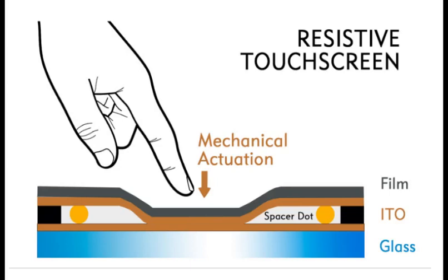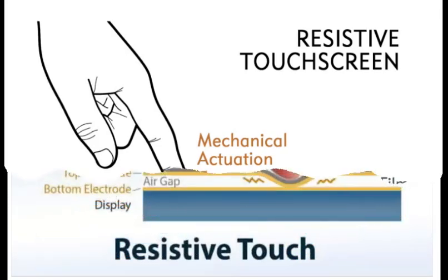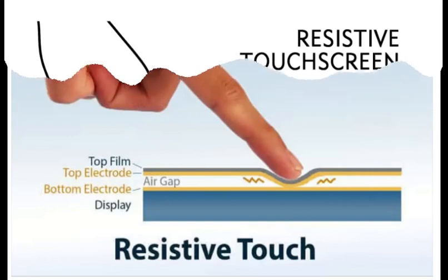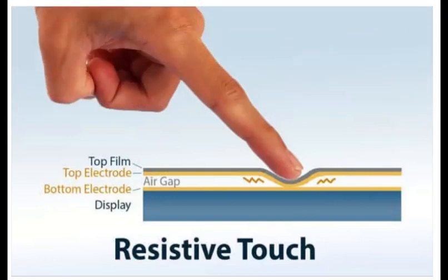Surface capacitive touch screen. Surface capacitive touch screen is the second most popular type of touch screen on the market. In a surface capacitive touch screen monitor, a transparent electrode layer is placed on top of a glass panel. This is then covered by a protective cover. When an exposed finger touches the monitor screen, it reacts to the static electrical capacity of the human body. Consequently, some of the electrical charge transfers from the screen to the user.